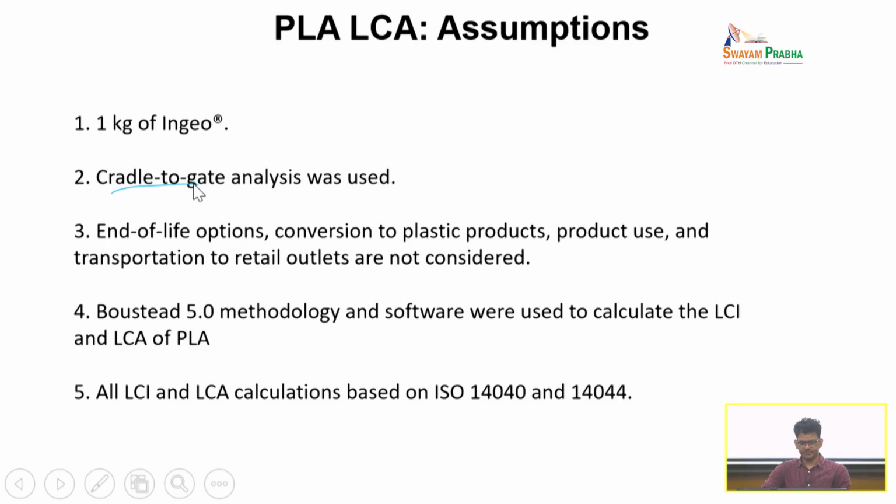Okay, so in this particular paper they have looked at all these processes. Assumptions, again as per the ISO standard 14040, have to be clearly mentioned, so that we know the limitations and applicability of the analysis. Here the basis is 1 kilogram of INGEO resins. Here also you can see it is based on cradle to gate. End of life options, conversion to plastic products, product use, transportation to retail outlets are not considered.